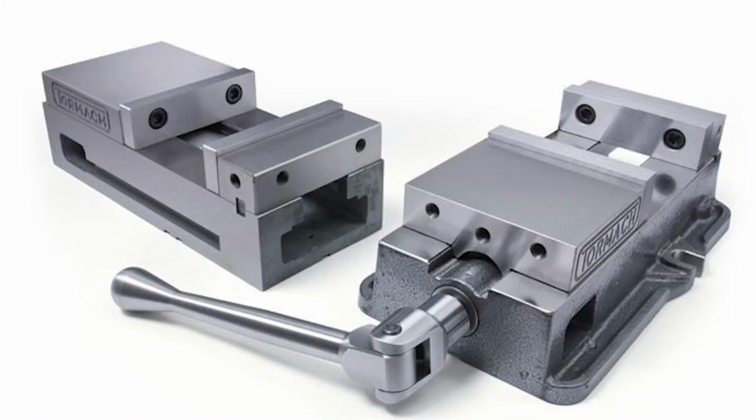We will be using the most common fixture in a machine shop, the machinist vise. It is important to know which length of the material needs to be clamped. If possible, you want to hold your workpiece with the greatest surface area along the vise jaws and the shortest distance between those two jaws.